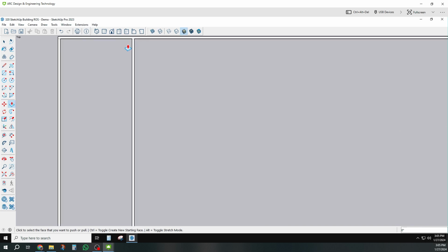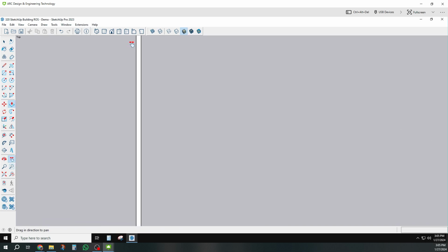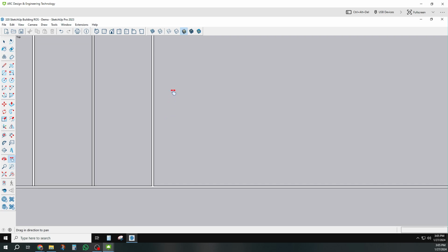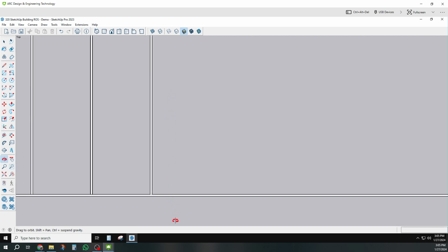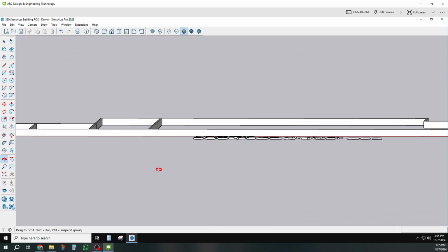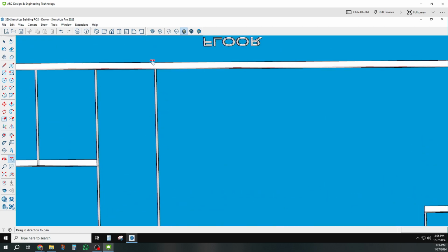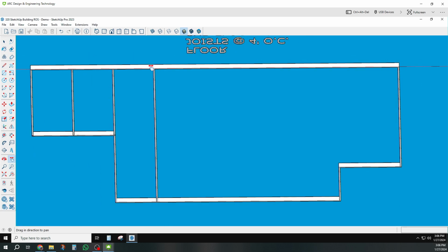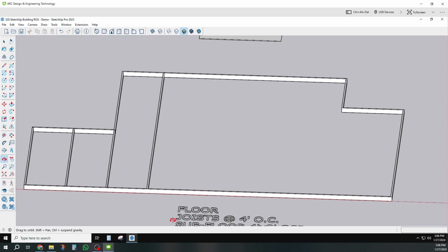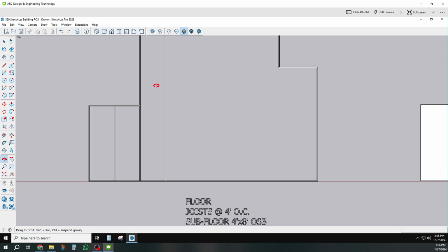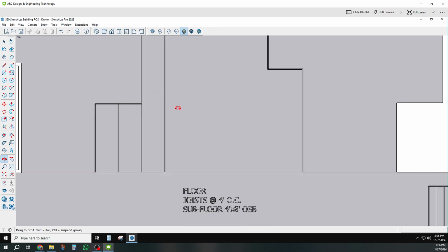And there's a few things that I want to do. So I see a line here up on top, and I see a line way down here. I'm going to have to see, though, if those lines exist on the bottom. That one does. And that one does. So that's okay. If those did not, I would have had to put lines in so that I can make it into a component or a group. So now I need to make those things into a group again.